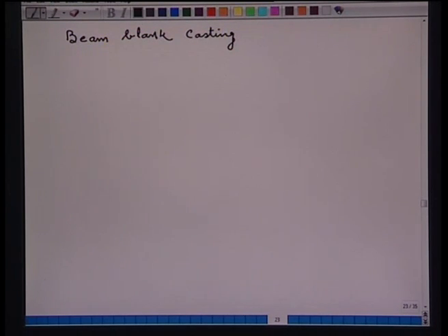Conventional methods require hot rolling of slabs, including intermediate hot rolling. That means we start from the bloom or billet, extensive rolling is required, and then we get a beam blank. Instead, a direct method for casting from liquid steel is in progress, and one of the plants has reported they are producing beam blank casting also.